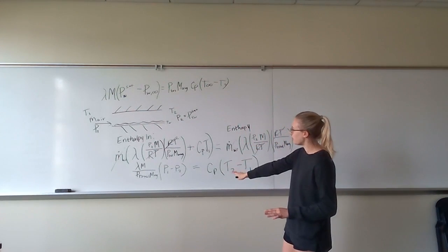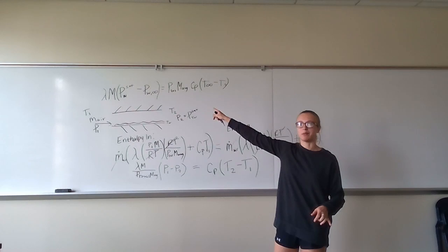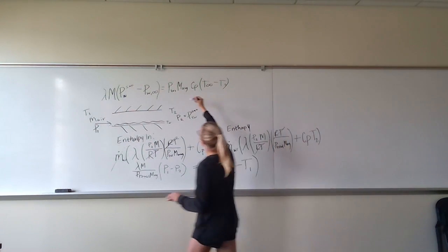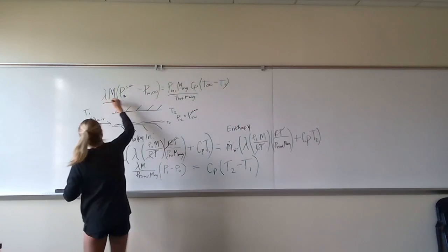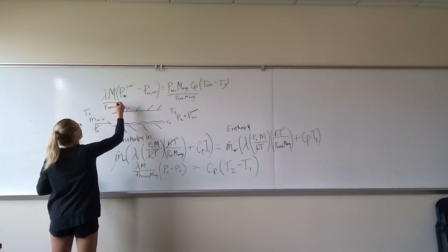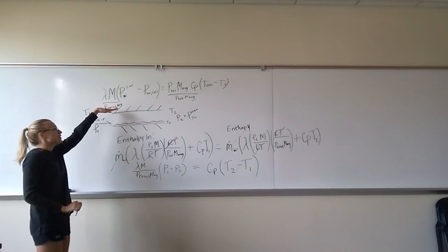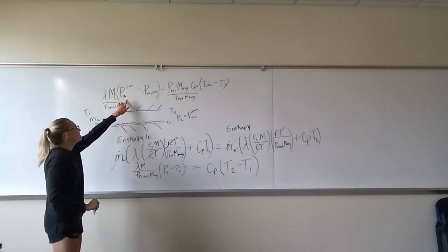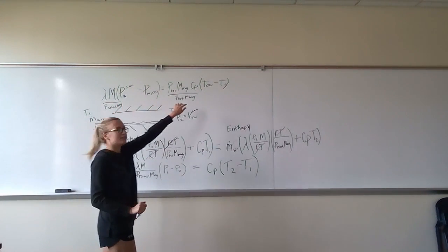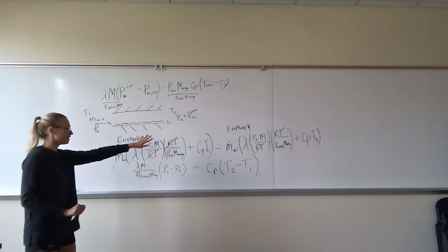So if we look at this equation, we can see that it is almost identical to the equation that we established in the previous portion of this exam. If we divide everything by the total pressure and the average molecular weight, we get almost the same equation, except this is in terms of the wet bulb thermometer and dry bulb thermometer readings. We can see that these are flipped, both of these are flipped, but if we negate this equation, they're very analogous to the terms down here.